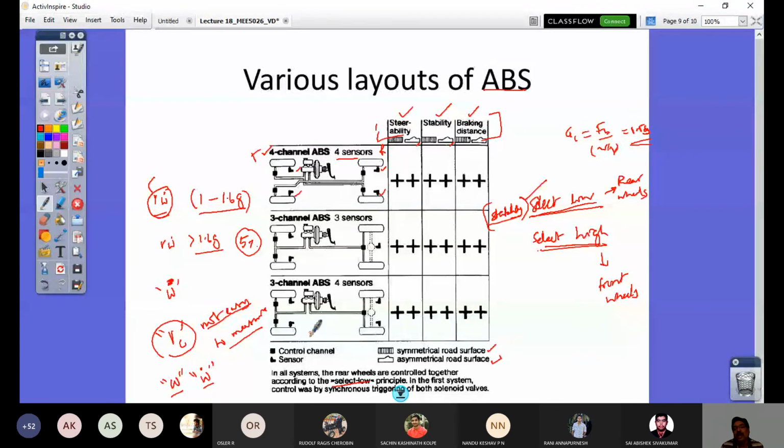That speed is held in the sensor memory for about 140 milliseconds, and then it is compared with these threshold values to determine whether a locking event is about to happen or locking is prevented. Accordingly, that means the wheel is under acceleration, then deceleration, then acceleration, deceleration. So that would be the equivalent thing.